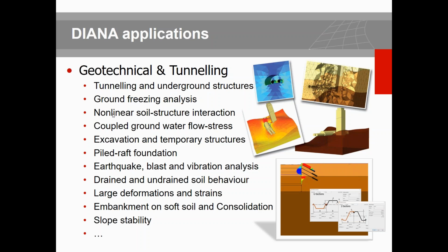A complete nonlinear SSI analysis, soil structure interaction analysis. So that's another powerful feature of Dana, that you can incorporate the structural failure as well as the geotechnical and the soil failure and interact them through the real nonlinear material behavior of the interface between. Then we have a concept of groundwater flow or seepage analysis, deep excavation and using temporary structures or supporting structures, pile foundation based on the different techniques that we have, and our pile element, which is a kind of embedded element, including the pile tip.